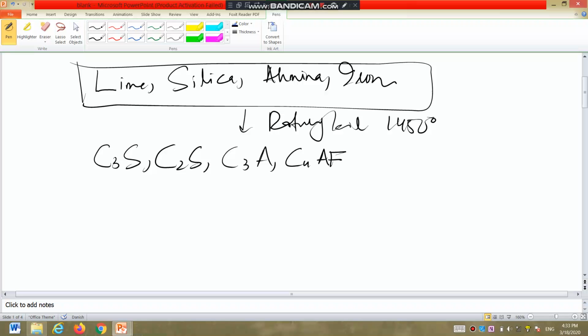These compounds are produced in the form of clinker, which is later powdered together, and another ingredient is added as well, which is called gypsum, which must be present from 2 to 3% or 3 to 5%. These are the main ingredients or the main chemical compounds produced in the cement bag that is being purchased from a store.